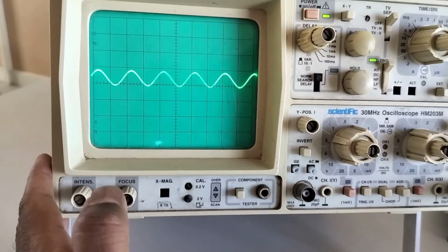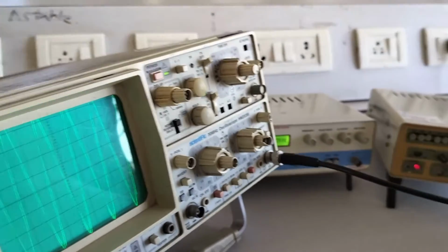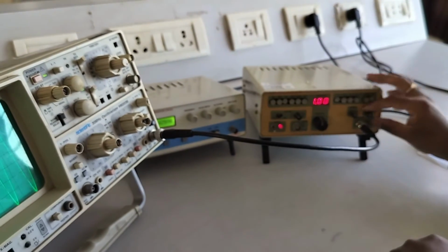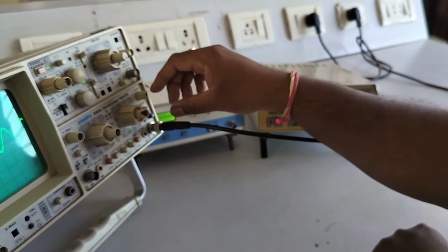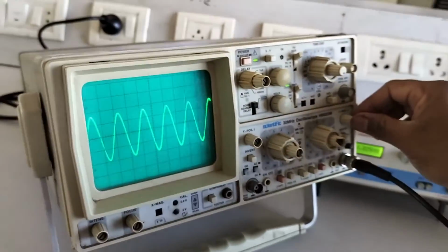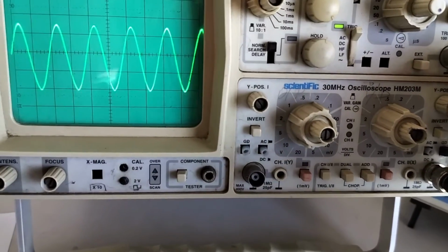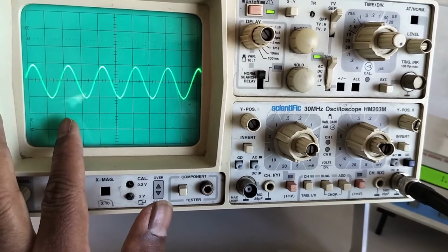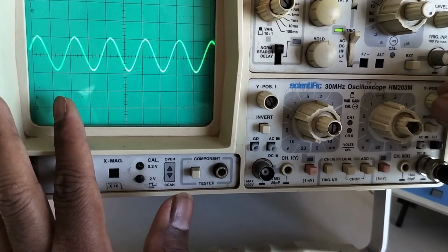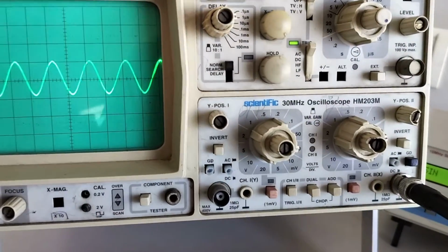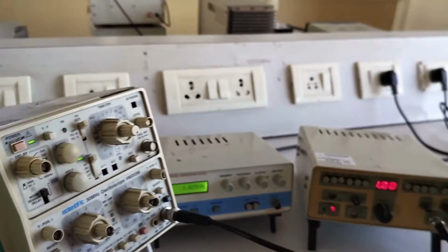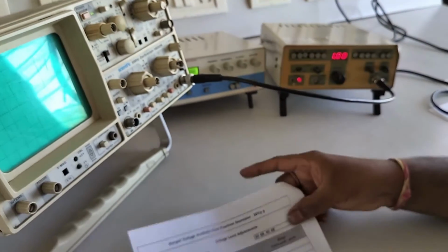Suppose someone asks you to adjust 100 millivolts. As I told, 40 dB is nothing but the 0.2 volts range, or 200 millivolts. The maximum will be 200 millivolts. What I will do is set it to the 50 milli position, and the signal covers nearer to 4 divisions. I will cover 2 divisions vertically, so that 2 into 50 is 100 milli you are getting. The attenuation position will be 40 dB. This is about the 20 dB and 40 dB attenuation. If you have doubt, you can go through the chart and make yourself perfect.